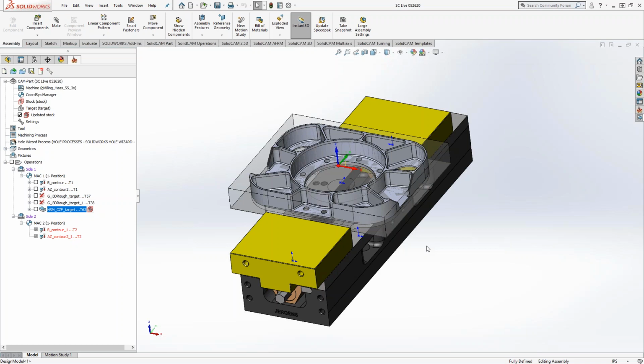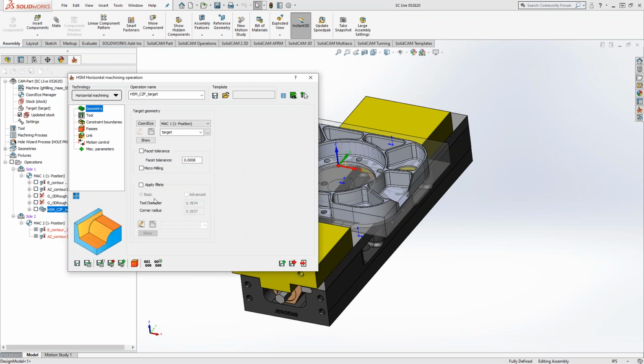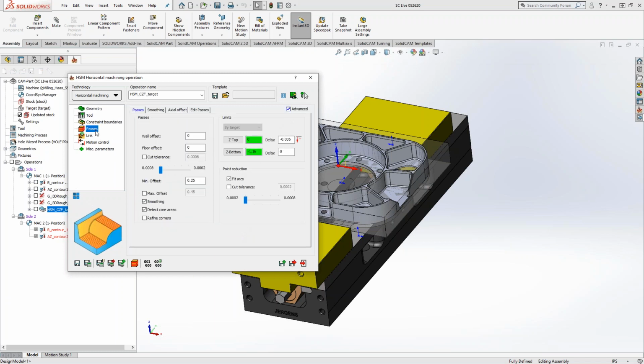Okay, so let's see. How can someone control tight tolerances? Tight tolerances with HSM is the question. Well, when it comes to tight tolerances, up on those walls, if we do have a tight tolerance in there, Edwin's bringing up a great point of tool compensation.